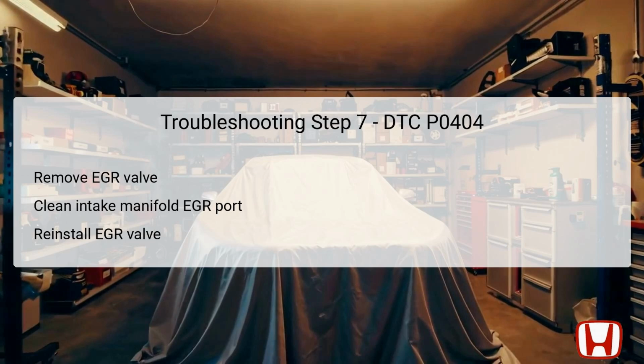Utilizing throttle plate cleaner for this cleaning process effectively dissolves and removes any obstructions, aiding in restoring normal flow through the EGR system. After ensuring both the EGR port and the inner passage of the EGR valve are free from dirt and carbon, reinstall the EGR valve securely in place. Finally, reconnect all dismounted connectors to ensure a seamless operation of the EGR system once reactivated.